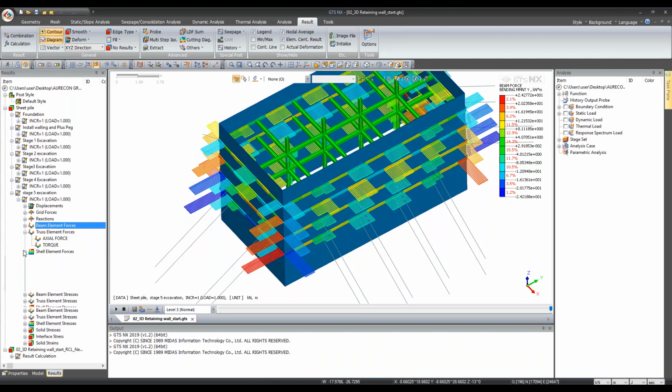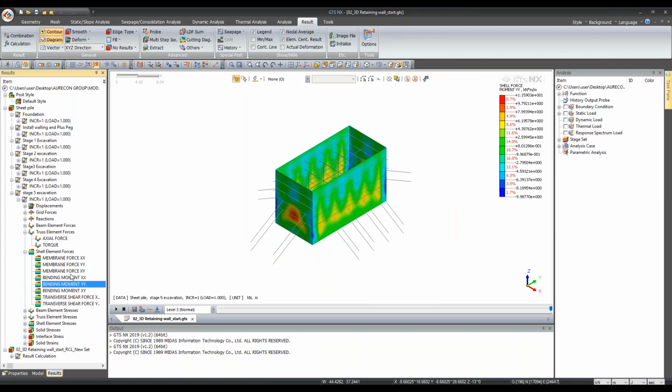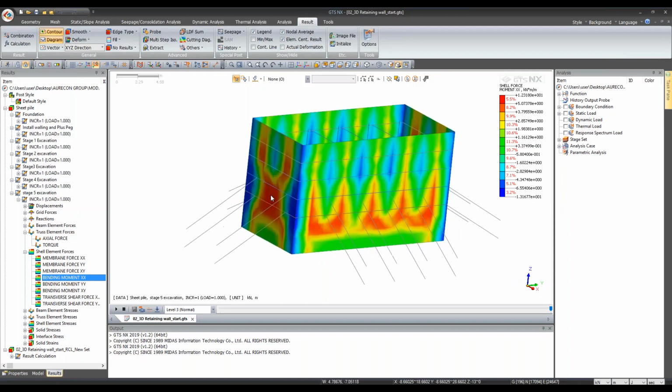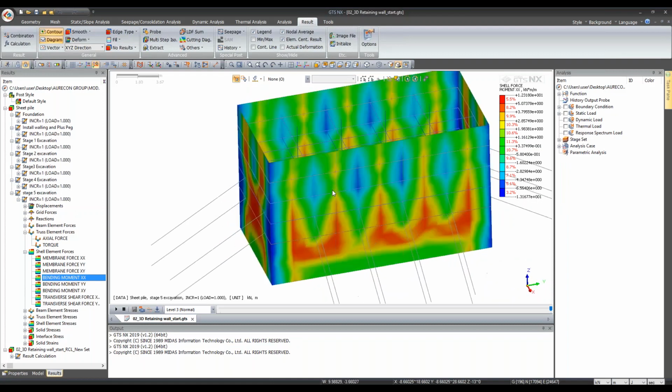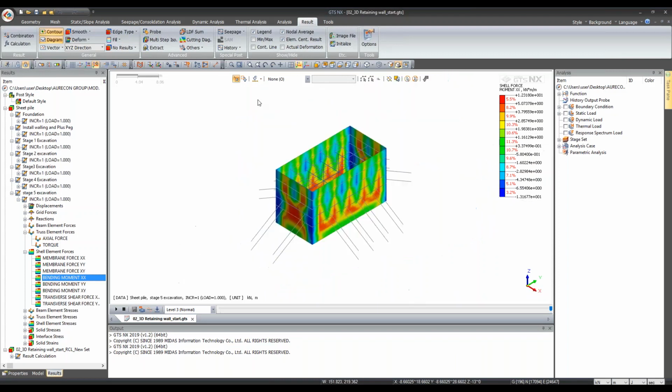And let's say I have considered sheet pile as well. So what is the bending moment diagram on a sheet pile? Because I'm considering this type of a plate element or a shell element, you can find the bending moment in the XX direction, in the YY direction, in the form of a contour. Wherever you have a lateral support of this type, we need to go for the bending moment diagram even for the sheet pile, so that we can come to know whether that pile is resisting the entire load or not. Lateral load and your lateral displacement can be easily found using these particular conditions.